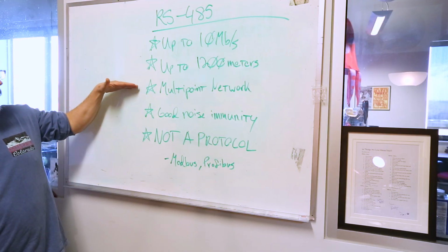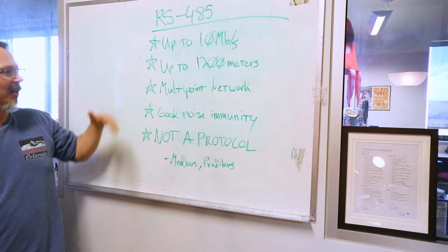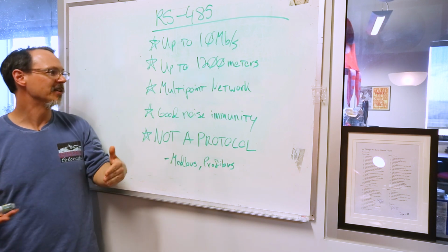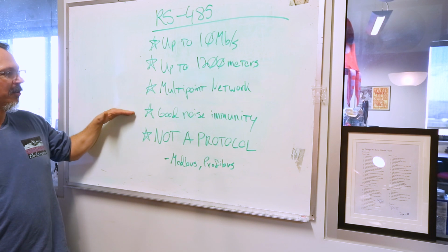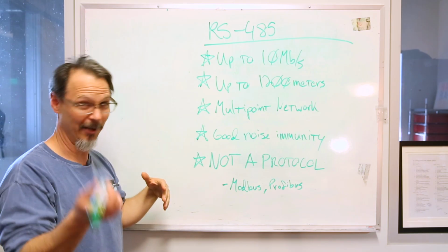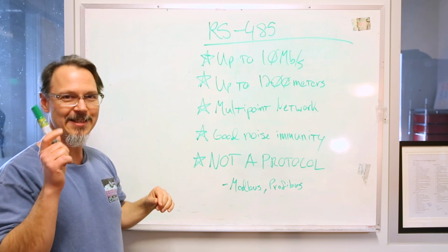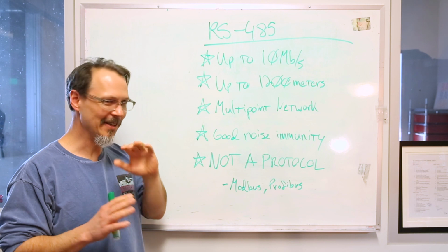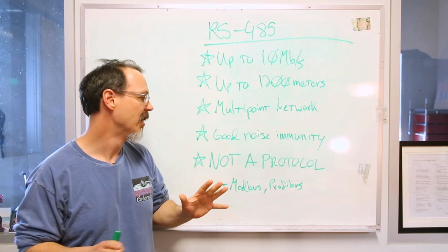It is a multipoint network topology, which is actually to say it is in a linear topology, and we'll talk about that as we go. It has really good noise immunity because it is a balanced differential signal, and we'll talk about that as we go. What it is not is a protocol, okay? It is only an electrical standard.